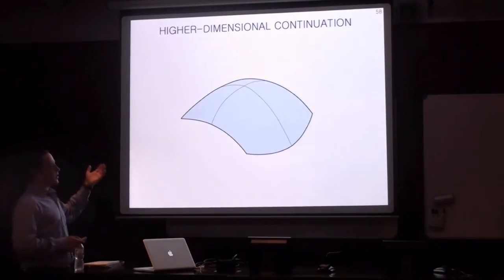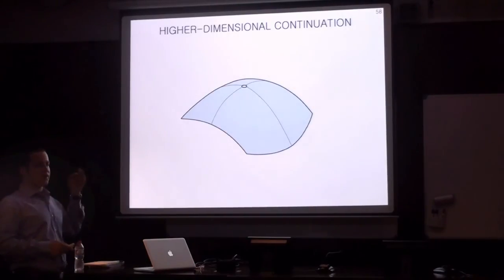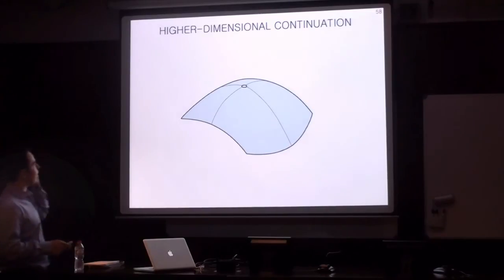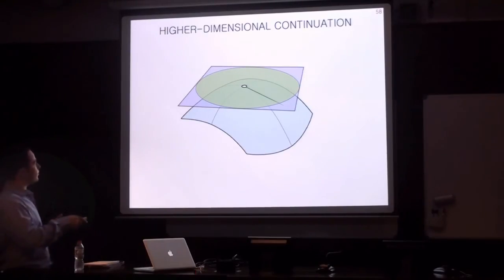Imagine that this is the manifold that we want to explore, and we have an initial configuration. So the first step is to initialize the first chart, and this is done by defining a ball on the tangent space of this configuration, together with a polytope that tightly encloses this ball. Then we have to select a point on the ball. This can be done, for example, by selecting a corner and finding the intersection with the ball.